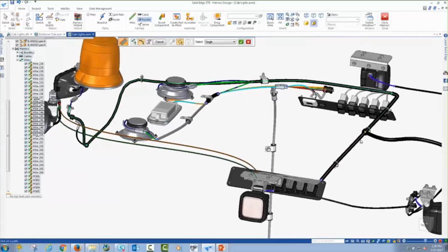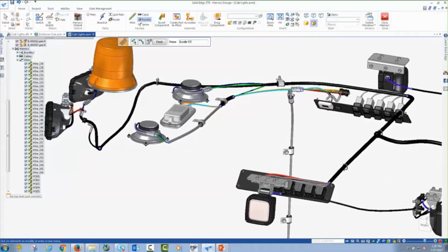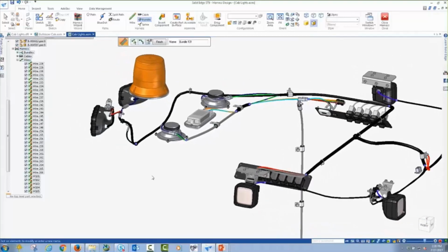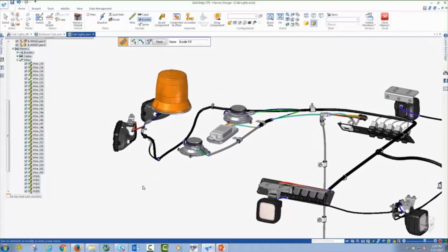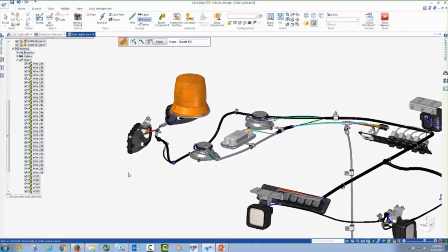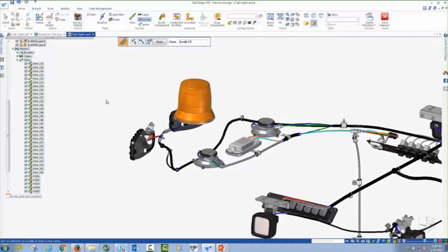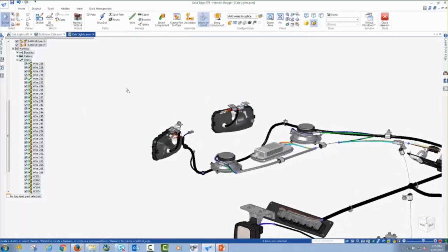these 5 different sections. What you'll notice Solid Edge do for us is take those 2 freestanding wires and reroute them all the way around to where they come out this end, but still stay connected where we told it to earlier. So again, very flexible tools to get your wires located exactly where they need to be and added to an existing bundle. And for documentation purposes, you'll see later on that those wires are going to be exactly where they need to be and documented correctly. Let's turn off a couple of components. Let's show a couple of other tools that are available here within Wire Harness.